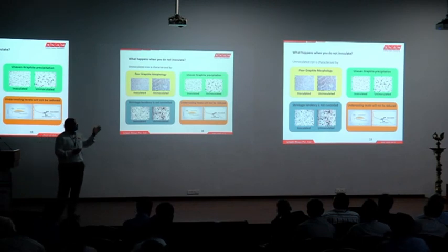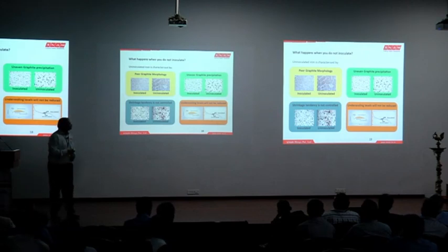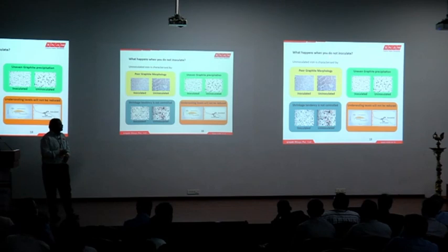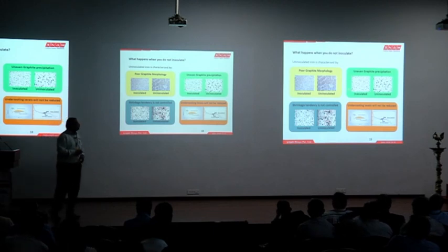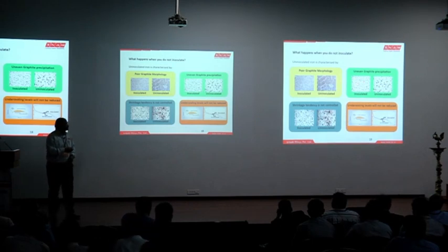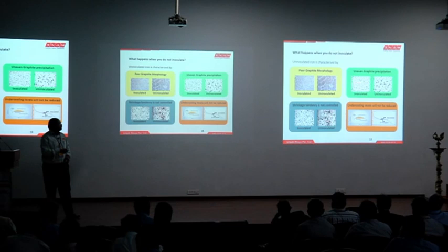So inoculation is added to ensure uniformity, that means non-defect structures throughout the castings, at least bare minimum. If you don't inoculate, you will be getting uninoculated, that means undercooled graphite, not 100%, but maybe at all the hotspot locations or fast cooling locations, which might be a working location of the final functionality. And uneven graphite precipitation. That means you might have the same amount of carbon here and here, but the amount of nodules formed in case of ductile iron may vary.